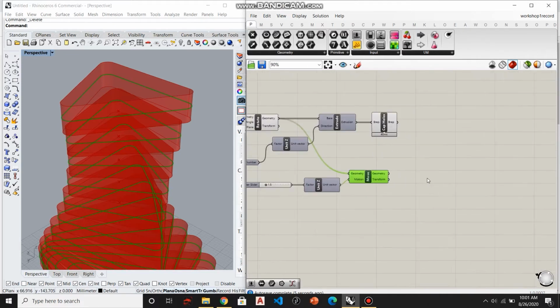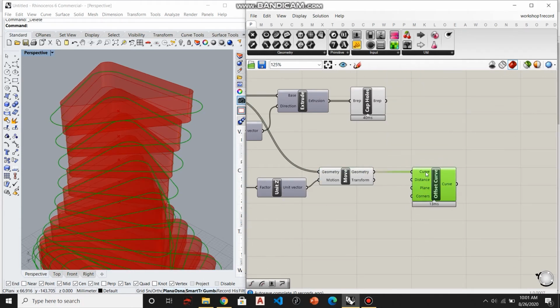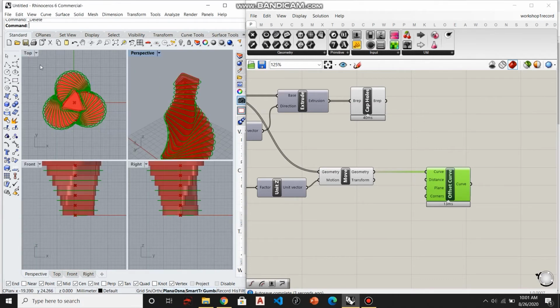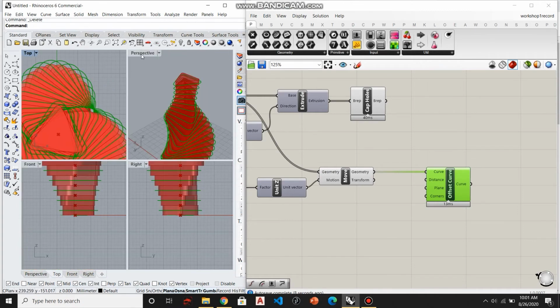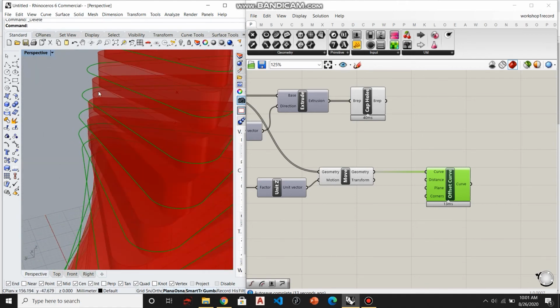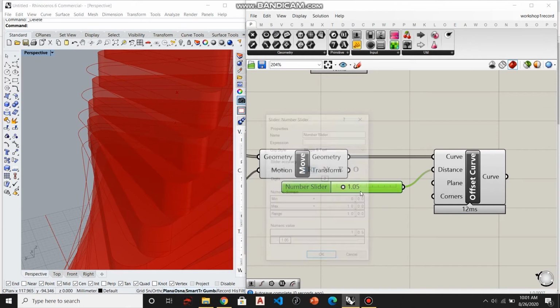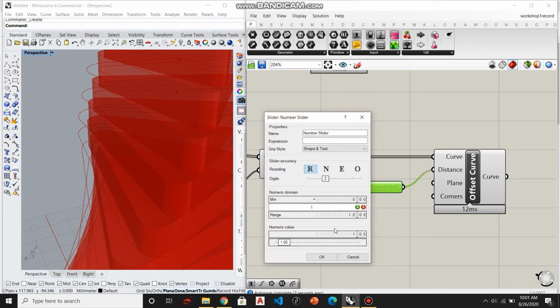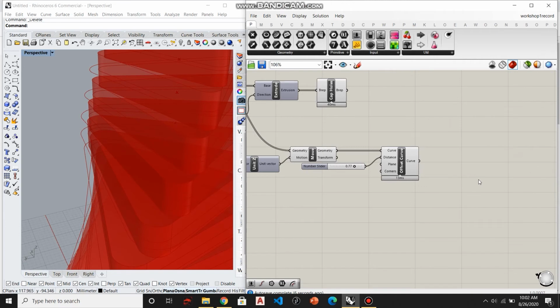And now I'm gonna use something called an offset curve and offset these curves. So what offsetting does basically is take the curves and offsets them to a certain distance. If you guys are familiar with 3D modeling, you know what offset means. So I don't want all this distance, so I'm just gonna change it to maybe 1.05 or something. Let's see what that, oh, that was actually larger. Let's say just 1, okay, and reduce this to maybe 0.72. Yeah, this looks good.